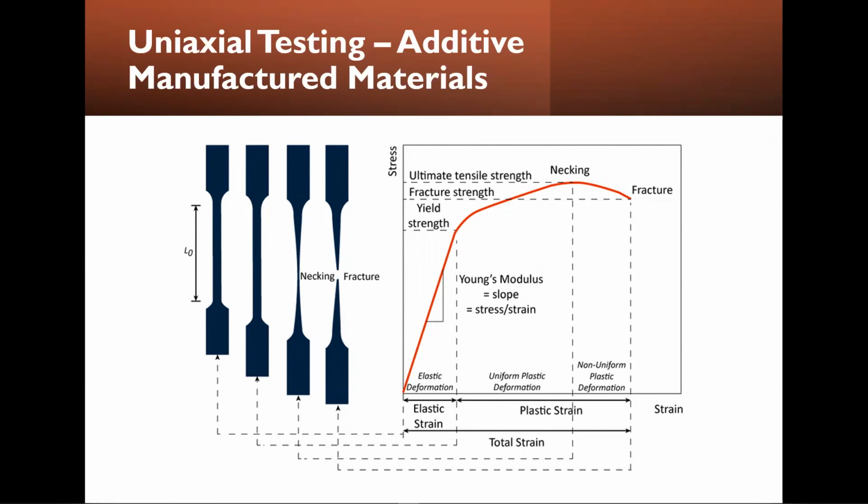By introducing a tensile or compressive stress at the initial surface of this AM material, we would like to see if the stress is becoming lower or greater due to this intrinsic stress effect.